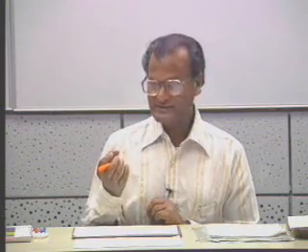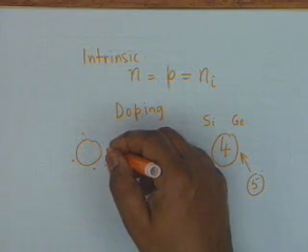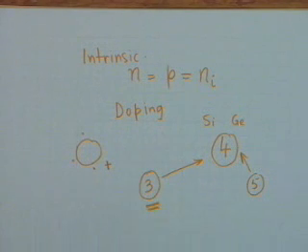All right? Is the bound one a positive charge or a negative charge? It becomes a negative charge, isn't it right? It can accept one of the electrons, which means it's a hole. When it accepts, it becomes full, but when it doesn't accept, normally it should have 4 in the silicon crystal structure. So it becomes an acceptor ion, a negative ion, charged negatively.